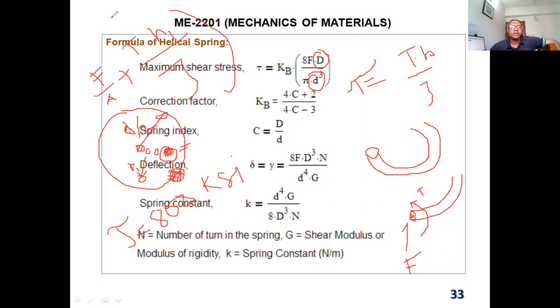Then you multiply by the correction factor, okay? It's possible to figure out, but when you want to design some parts, or figure out what will be the maximum stress, then you need to choose the outer fiber. You got your answer.